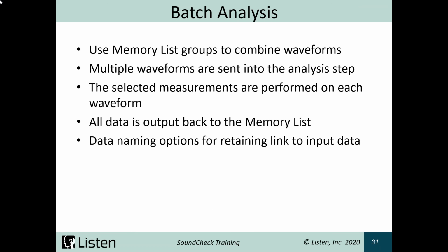One thing that's really helpful is to use batch analysis. If we have a microphone array with 7 microphones, and we're trying to capture all 7 and compare them to the same stimulus that created them, instead of having one stimulus step with 7 acquisitions and 7 analysis steps, I could create the one stimulus with one acquisition, and I could record in on all 7 channels.